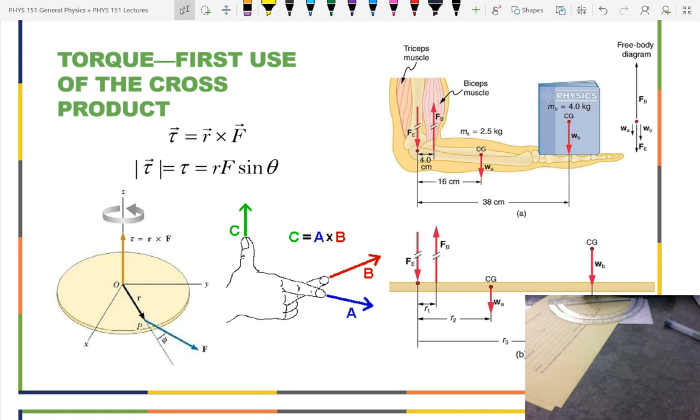You can get some screws that are left-hand threads. Left-hand threads, let's just compare. If you rotate it this way, a right-hand thread will go that way, a left-hand thread will go that way for the same direction of rotation. When would you see a left-hand thread? Well, you see them all the time if you work with gases of different varieties. Because you have some gases that are nice and safe, like helium and nitrogen. And so you make a regulator, and for inert gases, you just have this regulator you put on there, you screw it on, and everything's good.